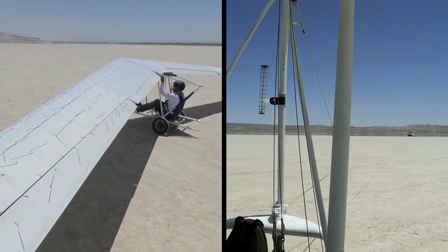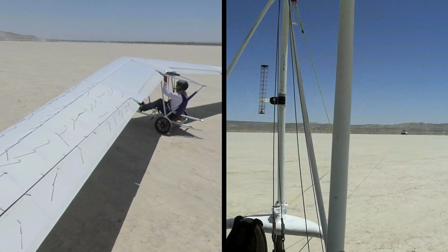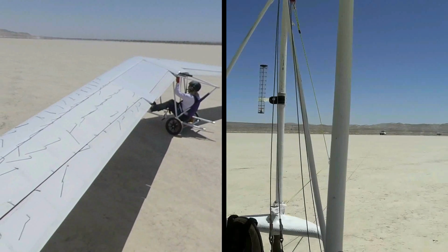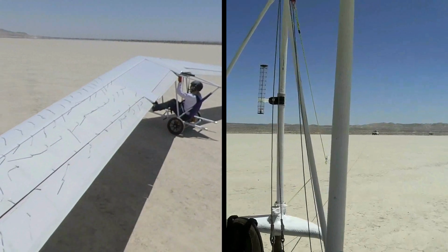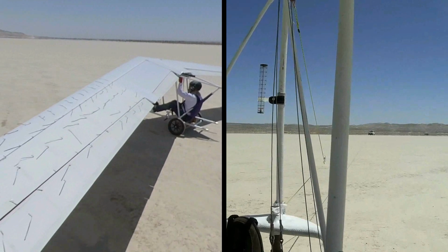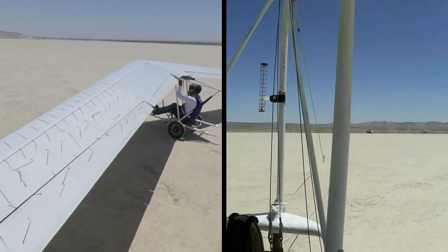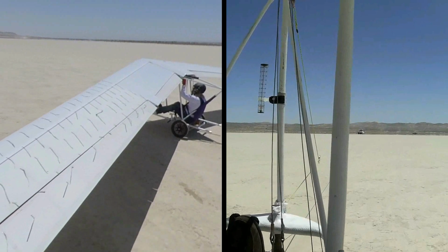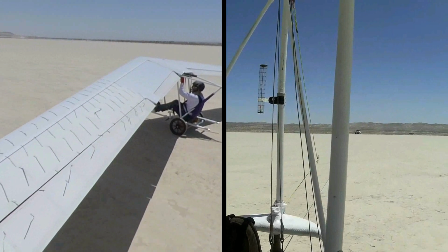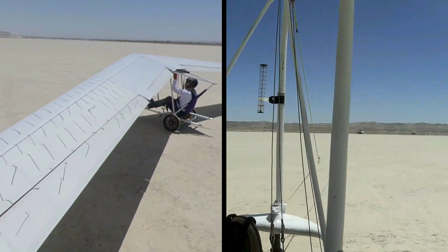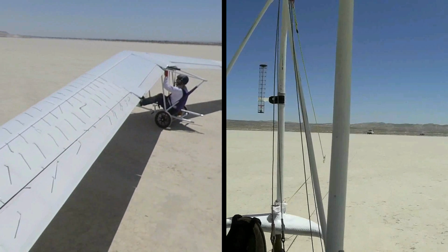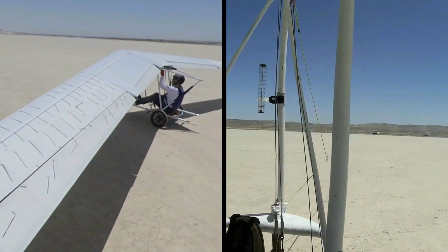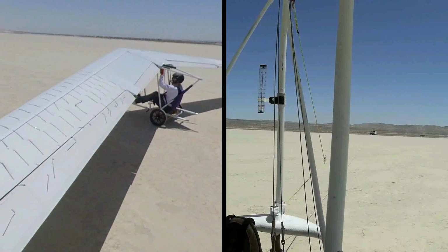And here we go. So you'll see that I'm holding down elevator, and I'm going to need that because the weight on the nose wheel is a little light, and I'm holding down elevator to help keep the nose on the ground. It's my only way of steering. You'll see that we're using a Y bridle to tow with, and watch the airspeed, watch that Y bridle. I'm going to pause this when I release so we can discuss the conditions of the glider at that point.